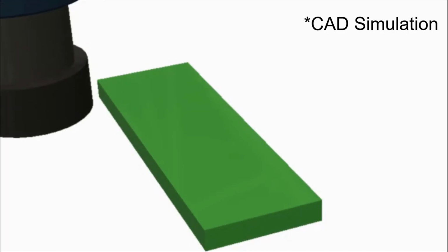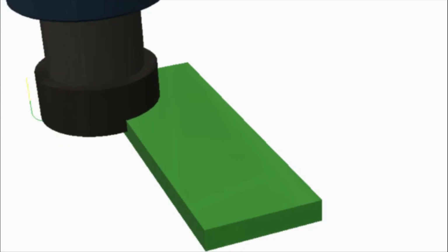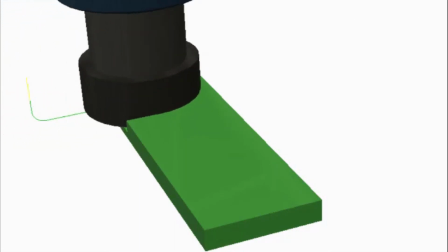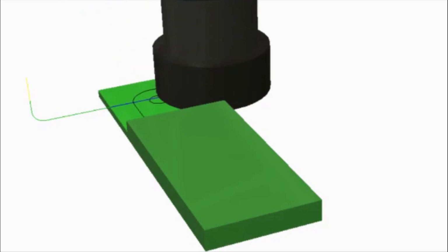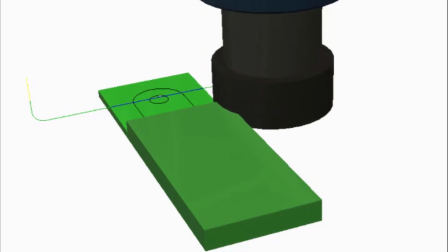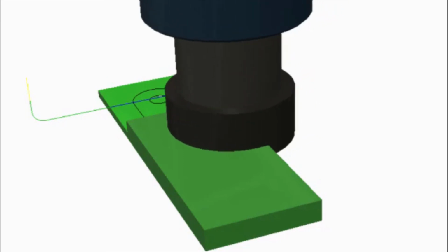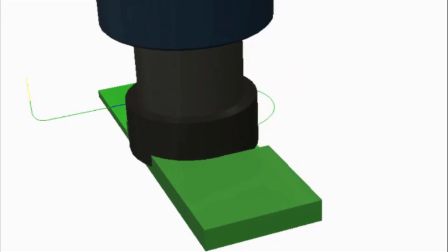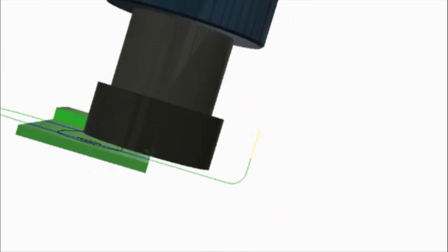Before we go, I actually wanted to show you an alternative way of doing things that involves only using a milling machine. Since I already extensively went through the initial method, I will only quickly skim through this and use CAD simulations to help support what I'm saying. This alternative method involves using a milling machine initially with an end mill to trim the thickness of the stock to the appropriate thickness. This first step can actually be used with the normal process initially if your stock is too large. I'm going to let this end mill make a couple more passes and then we can look at the next steps after that.